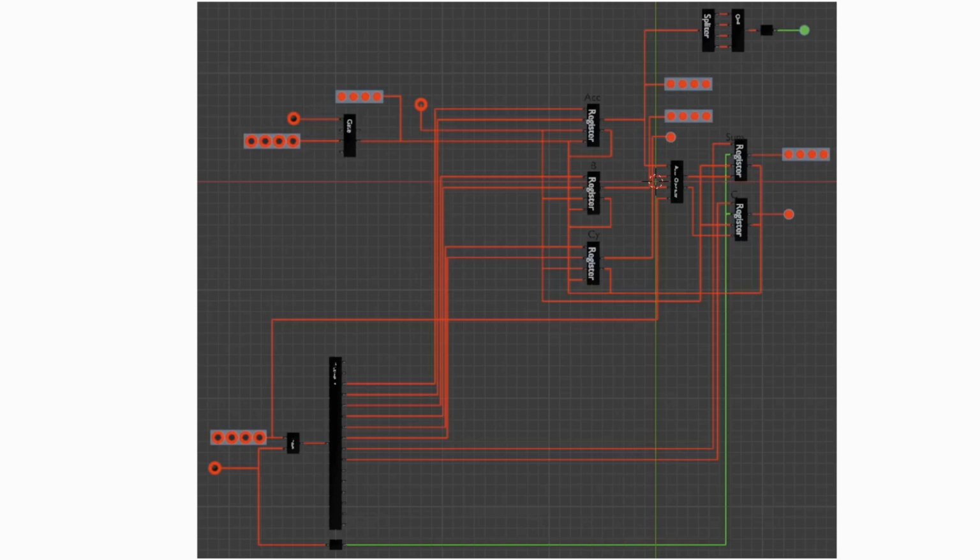And let's play around with it a bit and see how you would calculate 6 plus 8. The 8 must first be loaded into the ACC. This can be done using various instructions and is not important here. At the end there is the value 6 on the data bus. Now this value is written into the ACC.